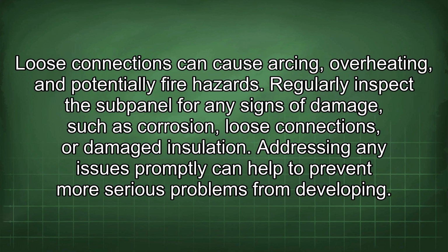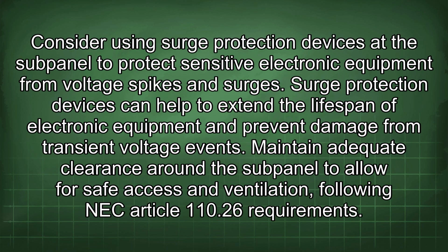Regularly inspect the subpanel for any signs of damage such as corrosion, loose connections, or damaged insulation. Addressing any issues promptly can help to prevent more serious problems from developing. Consider using surge protection devices at the subpanel to protect sensitive electronic equipment from voltage spikes and surges.